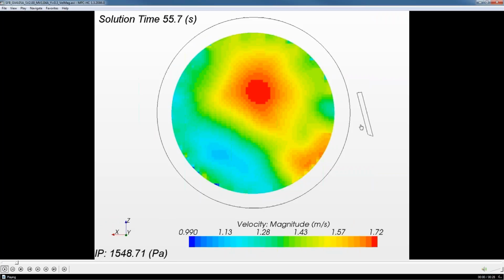Okay, there we go. So what we've got here is the flow's coming underneath the bed, and it's sort of offset and it's got an imbalance in it. It's what you end up with as the flow comes around, and you get a dead spot over here and a high spot over here. And so you can see that for a bed like this, you're going to have quite an imbalance on the bed, which is going to cause problems in terms of uniformity of what's going on in that bed. So if you've got a reaction taking place, or it might be that you're trying to dry a product in that bed, you can ultimately compromise your process if you're not careful.